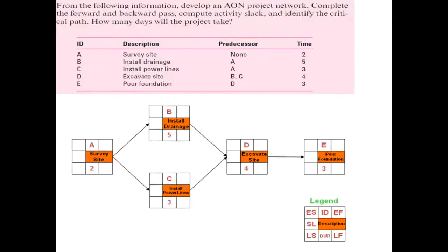Once we have done this, this is how our network diagram looks. Now here you can see the legends. The box over here indicates the duration of different activities, which is also given here. Then this top box basically tells us early start and early finish. As we said, we assume that the project starts on day 0. So that will be 0 and 2, 2 and 7.